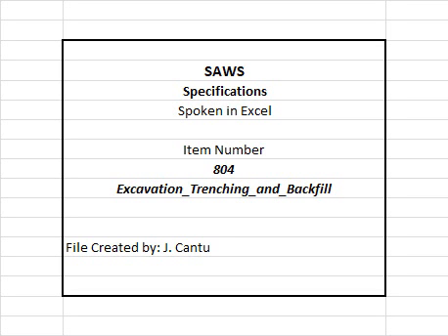If the contractor should encounter a section of an archaeological feature, such as an acequia, early Spanish irrigation ditch, or any other archaeological deposits during construction operations, the contractor must stop excavation immediately and contact the SAWS engineer and SAWS inspector, who will call the City of San Antonio Historic Preservation Officer at 210-207-0035 for an archaeological investigation as per Section 35-432.3 of the City Code.